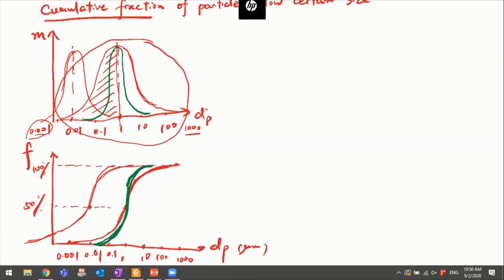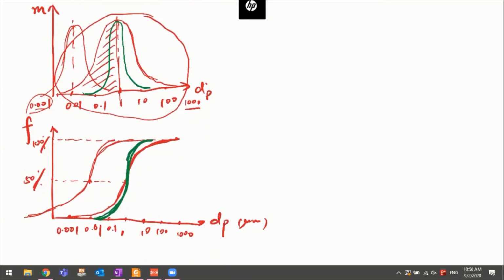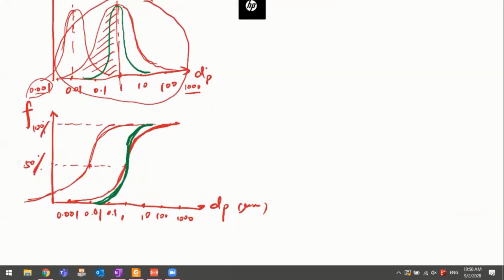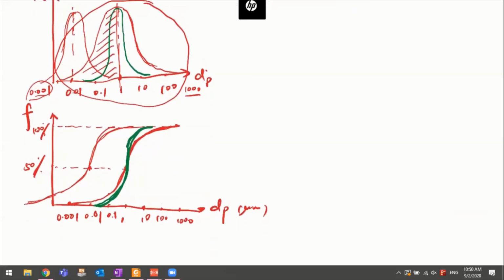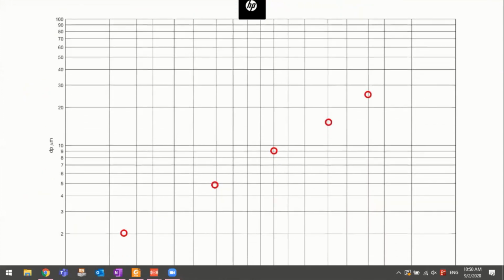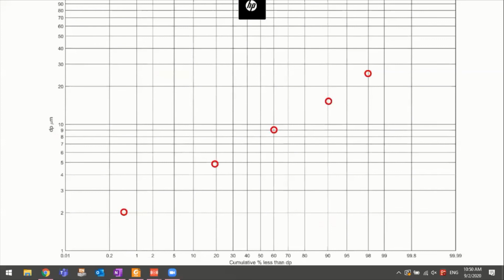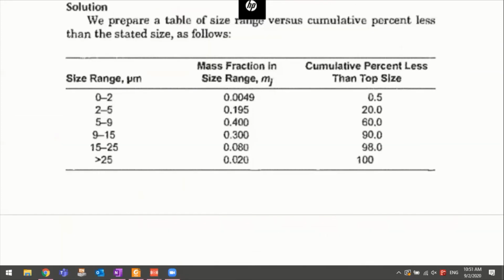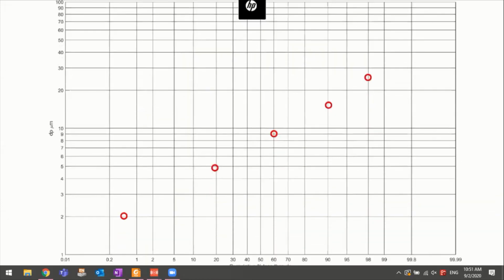All right. So people are going to use different ways to represent their size distributions. And next class, we're going to show a new plot that people can directly use to show whether a size distribution is log normal or not. On this plot, people also call this a semi-log plot. If we plot out all the measurement data in here, if they show as a straight line, then we can directly tell that's a log normal size distribution, okay?